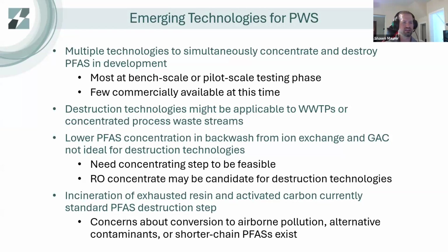But usually incineration is done at a central waste handling site. It's not done on site at the treatment plant. So you'll ship your activated carbon off or your resin off to another plant where that incineration is done at a hazardous waste handling facility. But there are those concerns. So other technologies may be slowly replacing incineration if it can't address these issues where PFAS can continue to get into the environment after that treatment process.